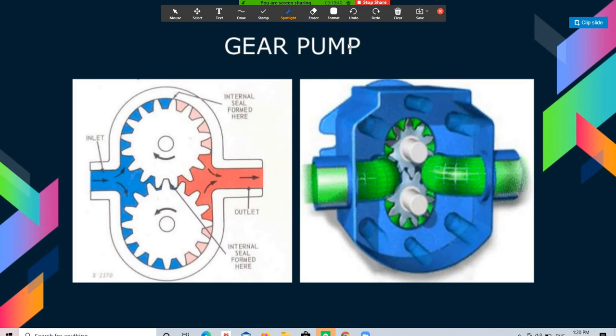The constant flow pump will deliver the same volume of oil for a given speed. The rate of flow will change with the change in speed. And in a hydraulic system fitted with a constant flow pump, when the piston of the cylinder reaches the dead end or when the spool valve is brought to the neutral position, the oil delivered by the pump is delivered to the reservoir either through the relief valve or spool valve.